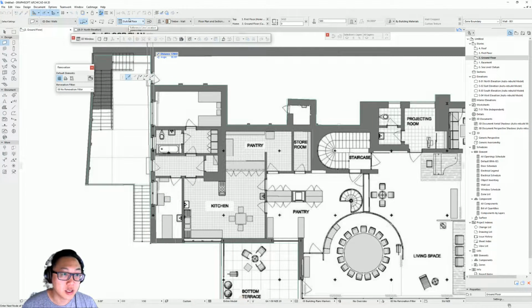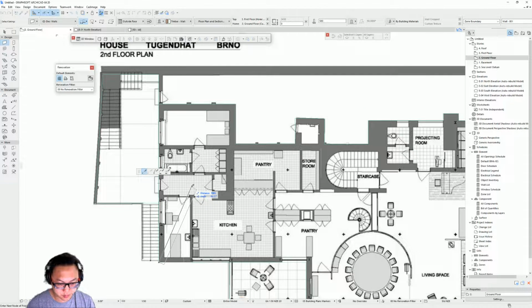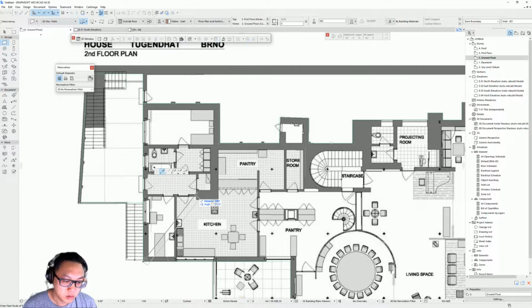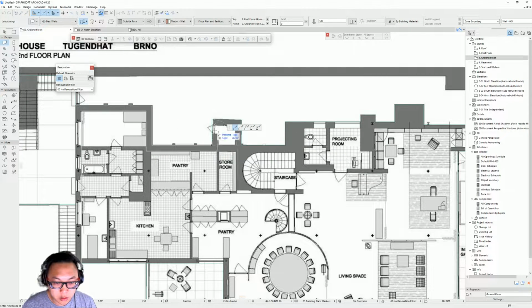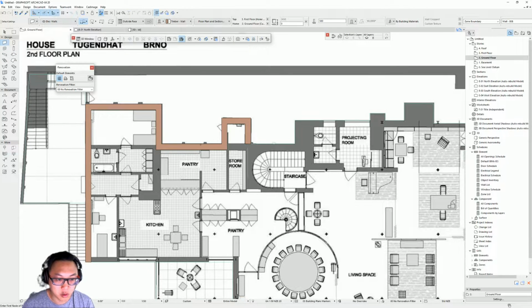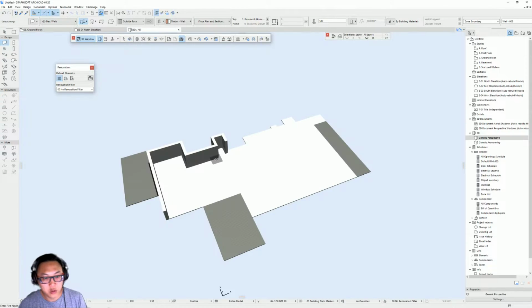You can see here the outside face is darker, which is on the left side of that wall. You can see it's darker, so that means the outside. Usually it helps when you set up different colors of surfaces, like you can have a different color from the outside to the inside. Okay, so I get one corner here, you can click that corner, and you can go all the way around the house doing this. If I double click, it will end it and create the wall. If you go into 3D view, that's what you get.